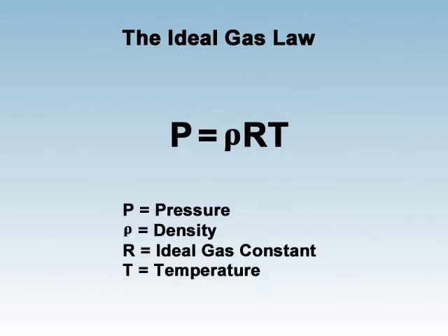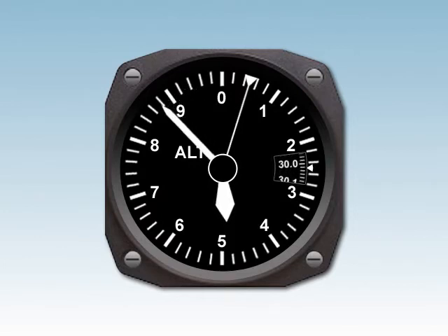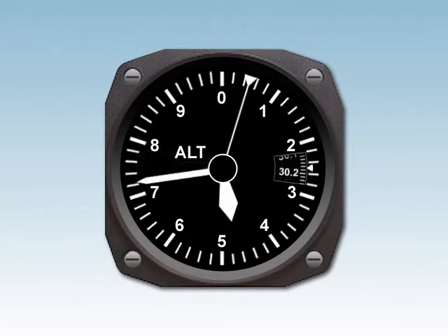On the instrument panel of an airplane, an instrument called the barometer would not be found. So why so much emphasis on pressure? Well, the altimeter is actually a barometer that displays information as altitude versus pressure. Although pilots refer to flying around at a constant altitude, such as 6,000 feet, they are actually flying around in an area of constant pressure.